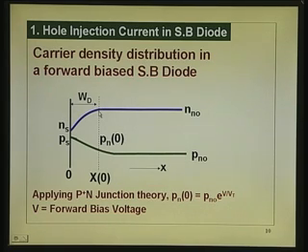In a p-n junction, you see an increase in the majority carrier if there are high injection level conditions, which we usually discuss in power devices where high currents are there, otherwise it is not there. So, you have got p-n 0 raised by that amount. What will be the current transport due to holes here? Now, you saw there is current transport of electrons from here to that due to the barrier.